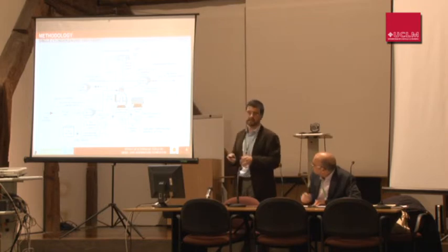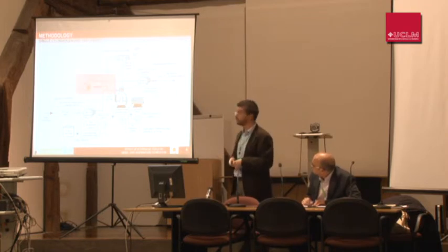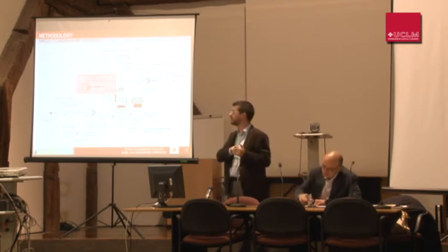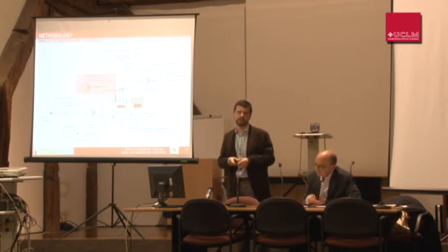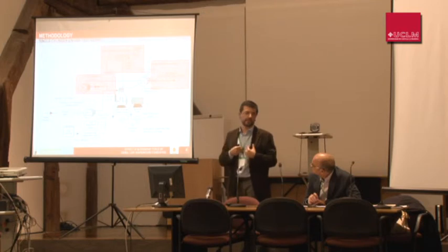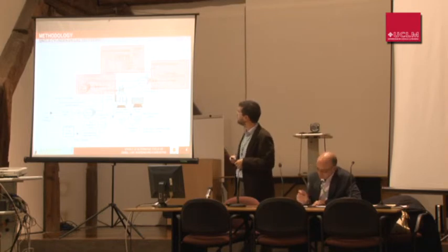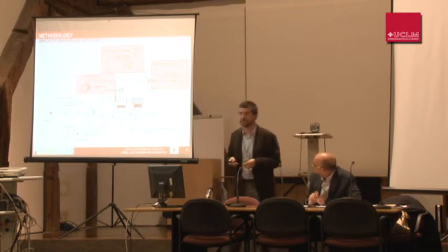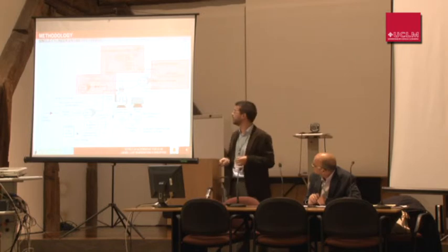This is a scheme of our facilities. Let me highlight just a couple of things. We can control EGR. We have kept it constant in this experiment, but we have the chance to change it in future work. These two things are the equipment that provides the results I'm going to show: first of all, the emission results, and second, the pressure trace from the cylinder, which allows us to calculate the heat release rate through a diagnostic model.